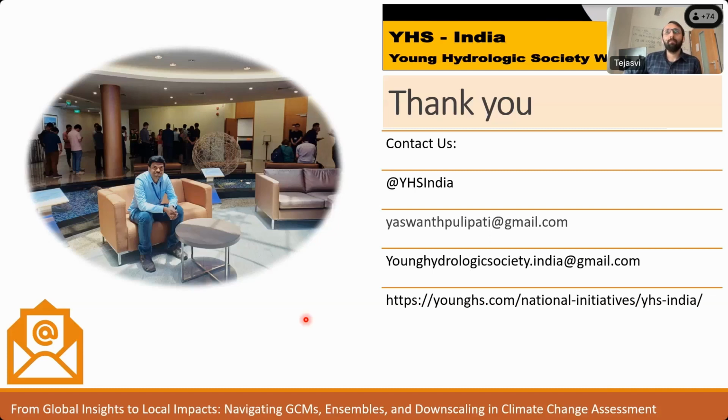When the main focus is on extreme events, I would suggest referring to some papers, especially a few published by Professor Subimal Ghosh and others. They have used regression techniques with two different regression models, one for rainfall greater than the 95th percentile and one for rainfall less than the 95th percentile. They concluded that the regression model for greater than 95th percentile rainfall is able to better adjust the extreme values closer to the observations, and this is the best way to use.